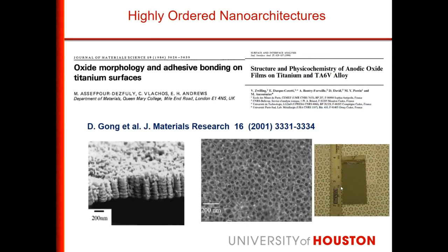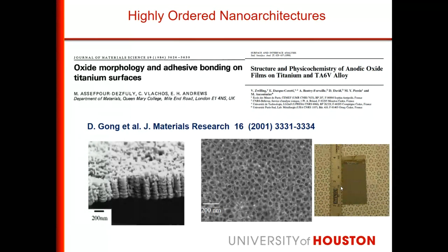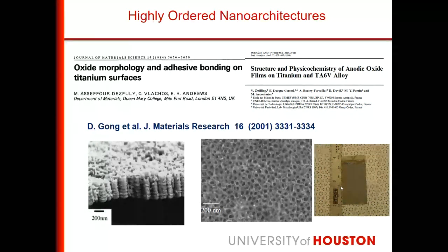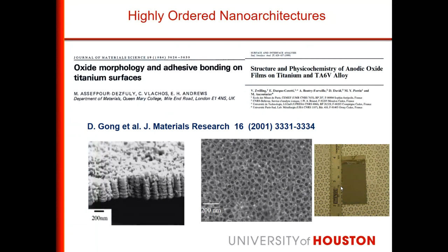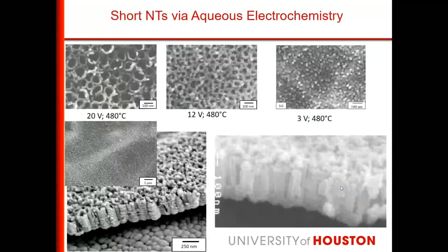This is the nanotube of titanium dioxide, which I participated in developing around the beginning of 2000. The length of the nanotube was around 0.5 micrometer, but the diameter we can vary from around 15 to 20 nanometers to 400 nanometers. A large range. This is a nanotube sample with this gray region covered with the nanotube, and the top surface is the substrate, which is the titanium foil. So these are different images of the nanotube structure.